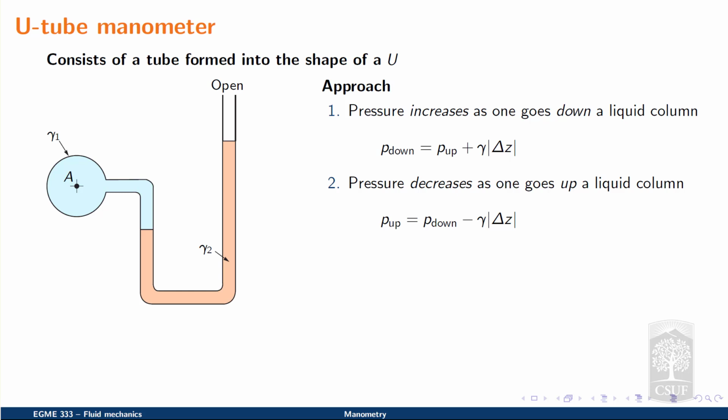For example, if I knew the value of the pressure at point 3 and I was interested in the value of the pressure at point 4, I could argue that the value for the pressure at point 4 should be lower than the value of the pressure at point 3 because point 4 is at a higher elevation than point 3.